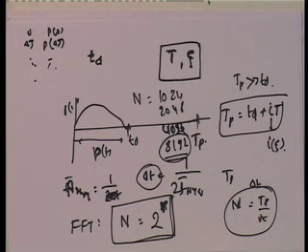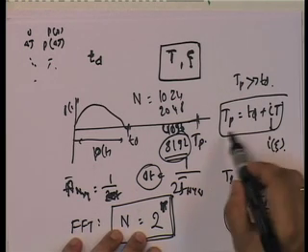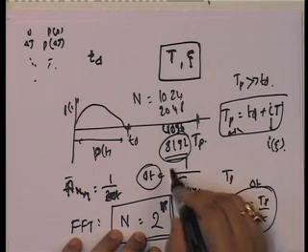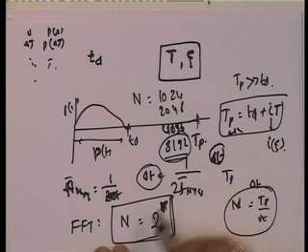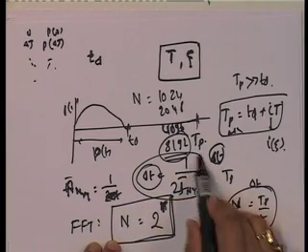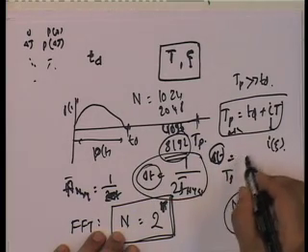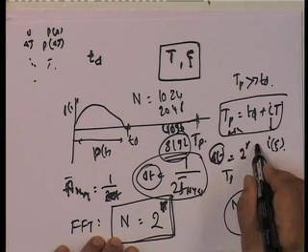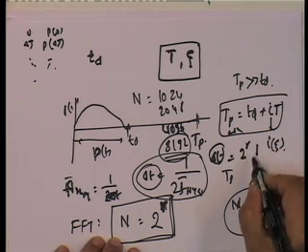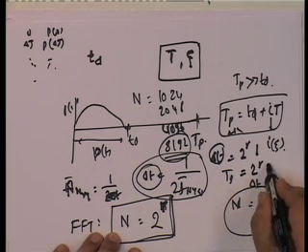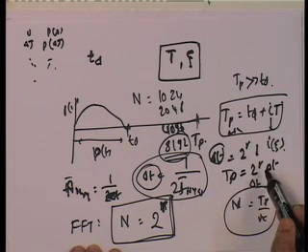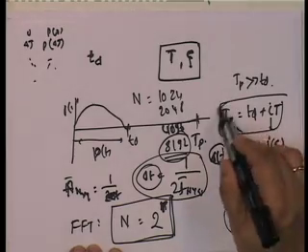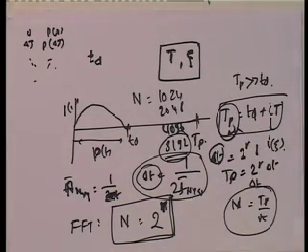So, that is all that is, and then what happens is, this is the minimum Tp, and then what you do is, delta t from this. Once you know delta t, all you do is you take Tp equal to 2 to the power of r delta t, where this is the Tp that you defined, and 2 to the power of r delta t is more than this minimum value that you require. And that in essence is the discrete Fourier transform.